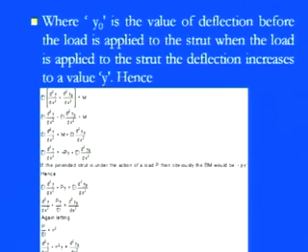So in that particular pin strut where the pin joints are there, the bending moment is always coming in this way. So we need to consider minus Py in terms of the M. With that consideration, what we have now is d2y by dx square plus P into y over EI equals d2y0 over dx square.